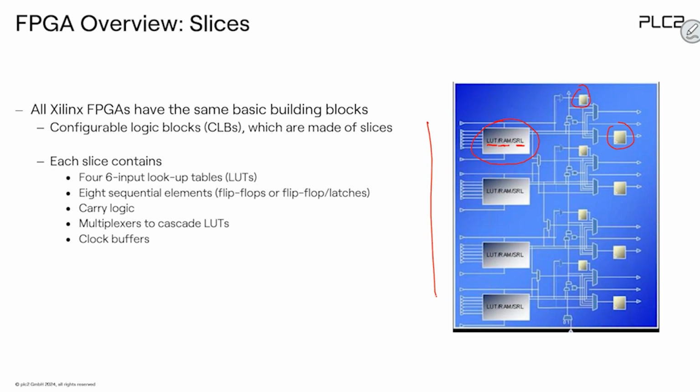There are some special logic elements which are built in, for example this one and this one. If you look a little closer, you will see this is some kind of path entering the slice and leaving the slice. In this case, it would be the carry logic. Whenever we need carry generation, carry is usually involved in a sum, A plus B, or in A minus B. That's also a borrow, which is also some kind of carry involved here.